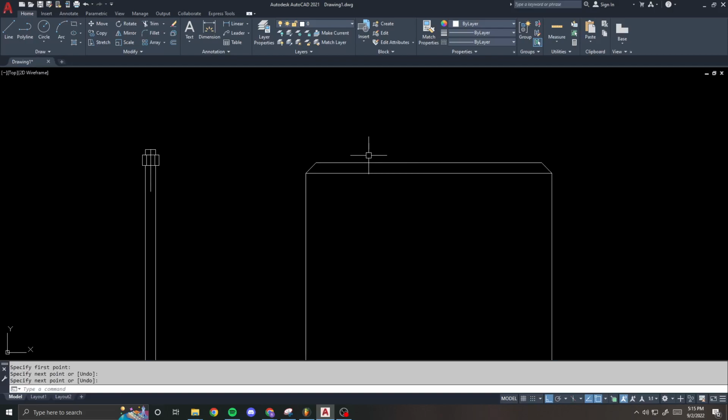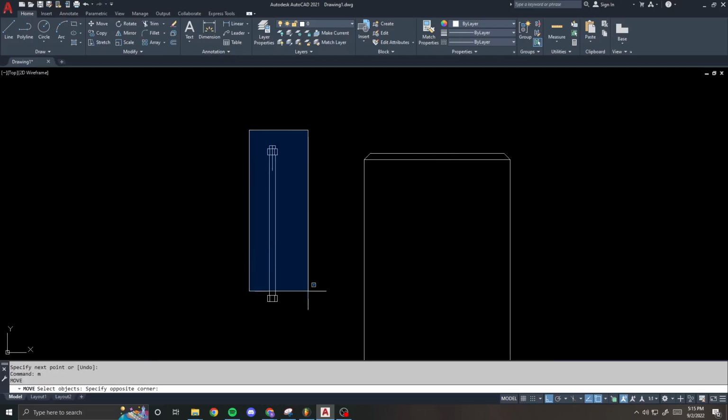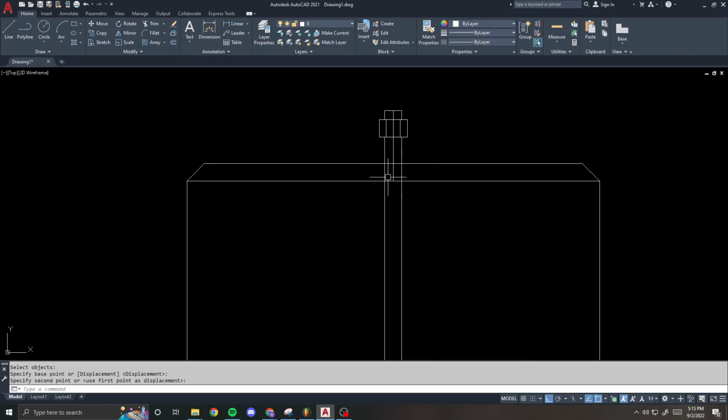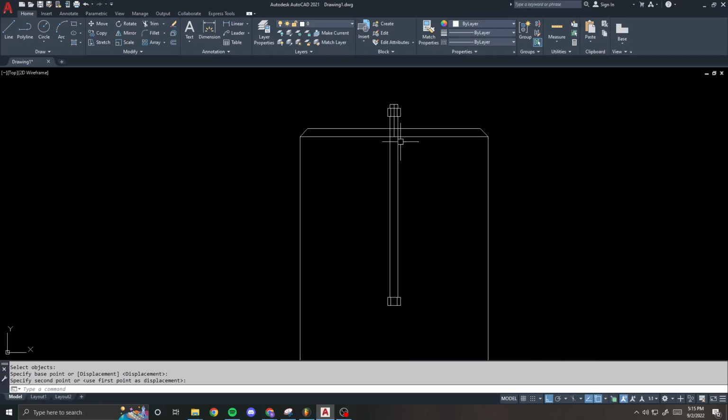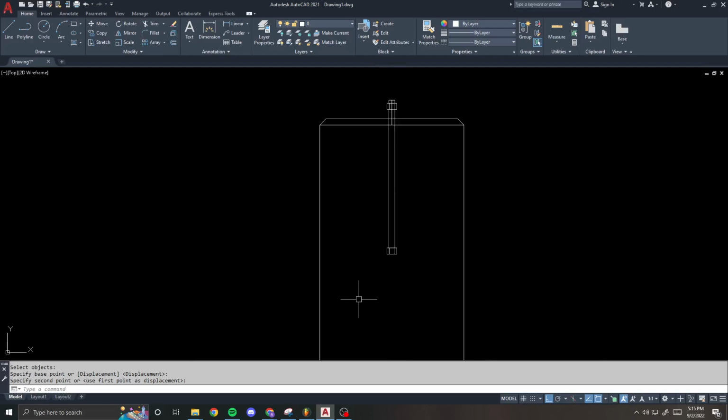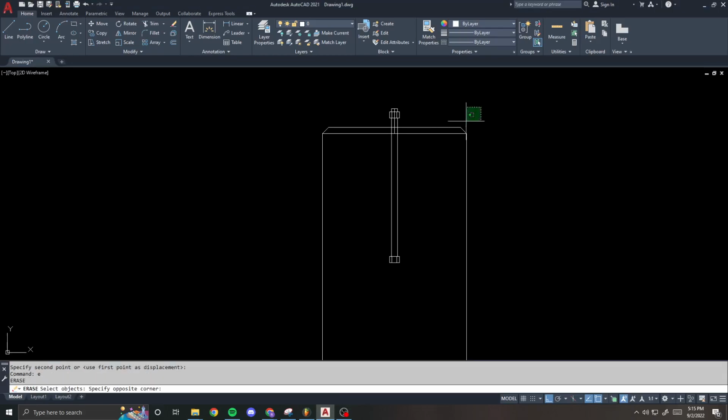And your grout pad may or may not look like this. You usually just chamfer the edges, okay? And our projection starts from the top of concrete, not the top of the grout. Okay, so here's my projection. This is the insertion point of my block. Now what we're going to do is make a bolt that stretches all of this downward and upward. Okay, projection needs to go up, but total length needs to go down. And we may have to tweak it a few times to get there, but we'll get there. All right, so let's move on.